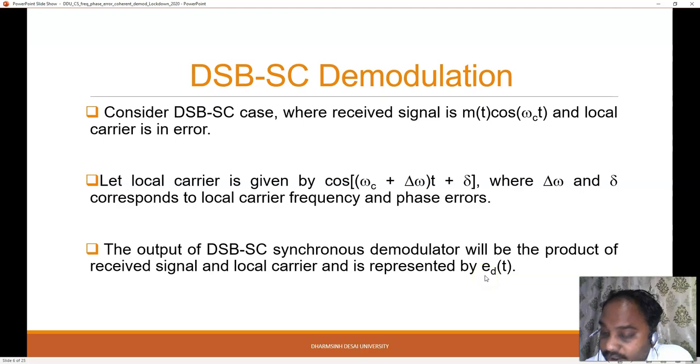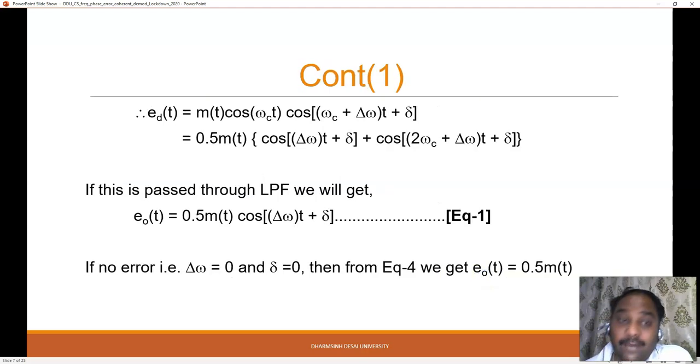It's not an output, it's a detector. Then I will pass it through a low pass filter. Okay, so I'm getting something like this: m of t cos omega ct. Applying some trigonometric identities, multiplying and dividing by 2, I get 0.5 m of t...